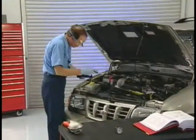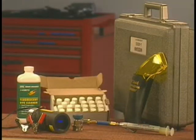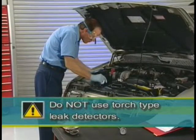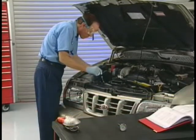The two common leak detectors are electronic leak detectors and fluorescent dye leak detectors. If you still have a torch-type leak detector, throw it away. Dangerous gases can be produced using torch-type detectors on R134A systems.